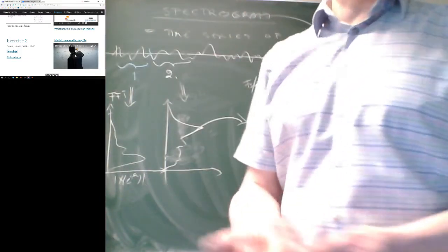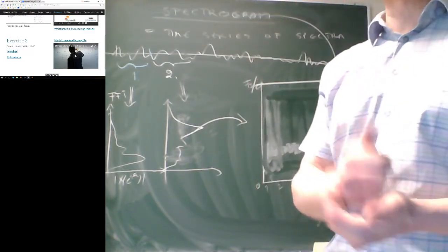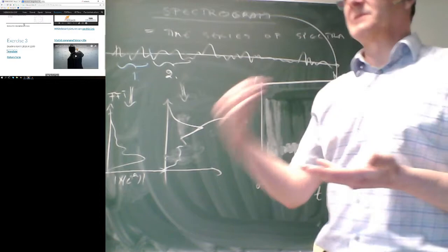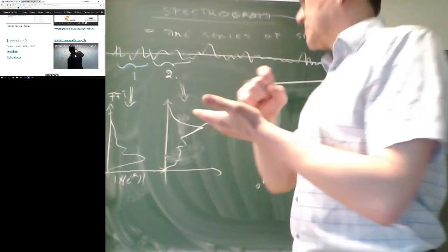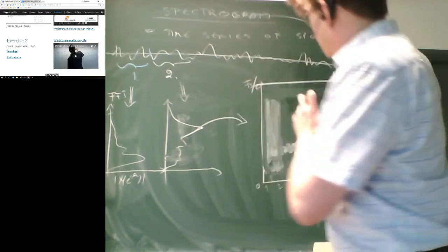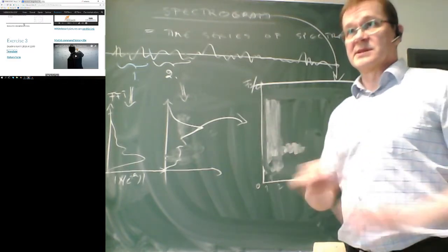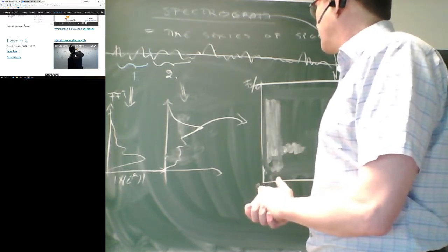On time base you cannot really do it, since voice samples are also very random. If I try to speak exactly the same words time after time, they still do not correlate in the time domain, because there are still some small changes, and even a tiny change at the beginning will make the correlation evaporate. But on the spectral plane, you can start correlating the spectral images, and that is a totally different thing. Good. All right.